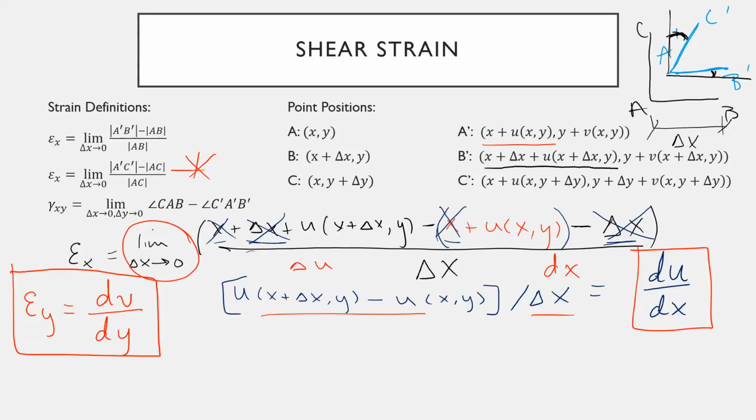So the cosine of theta equals what? Small angle assumption? Yeah, so cosine is adjacent over hypotenuse. If I'm telling you your hypotenuse is essentially the same, cosine of theta is going to be 1. So if you have this triangle that's a very, very small theta, that horizontal leg is essentially the same as the inclined leg, so the cosine is 1. The sine of theta ends up being approximately theta, which means tangent of theta, which is sine over cosine, is also equal to theta.